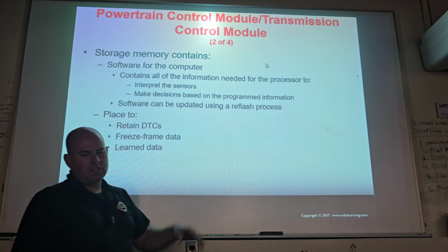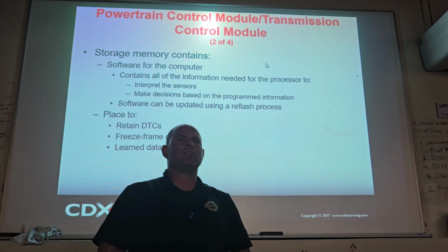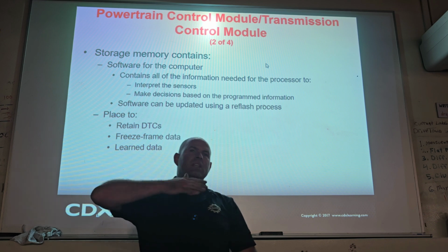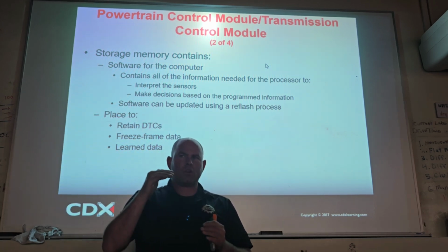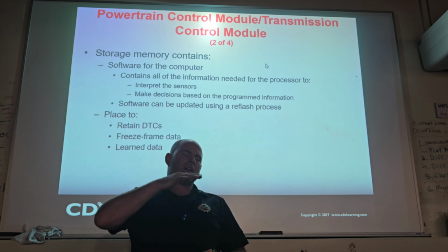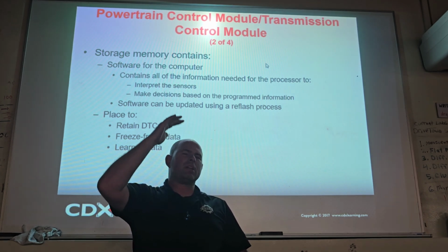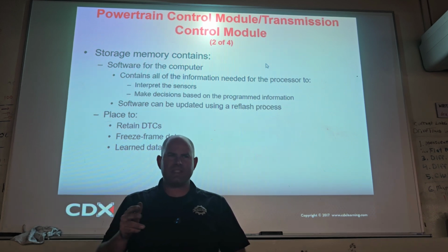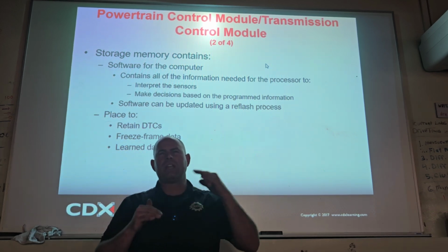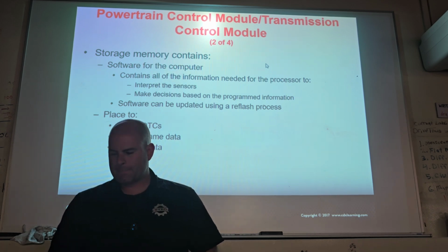And then you can even see, when it says learn data, that a lot of times will tell you in a transmission, is it using those SL solenoids to increase your clutch volume index? Because you can actually see that it's adapted and adapted and adapted. That can give you a pretty good indication that, hey, that clutch is wearing. The more it adapts, that's probably because the clutch is worn more. You can actually see that.